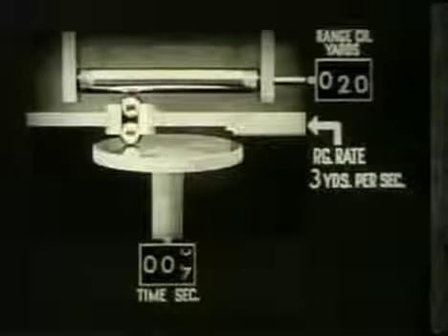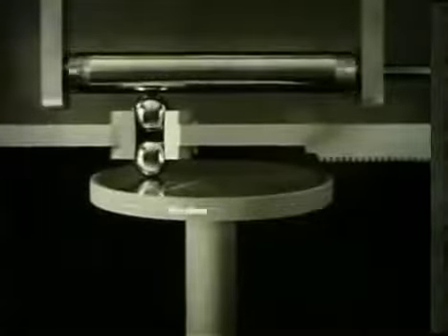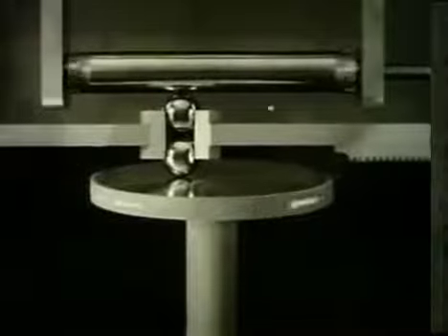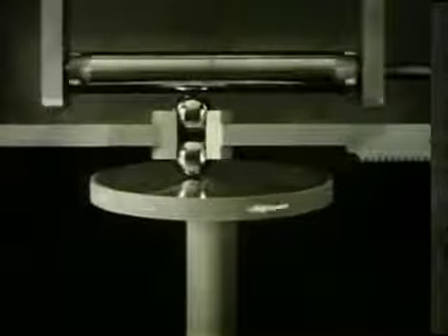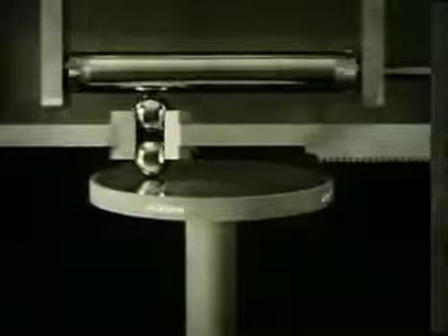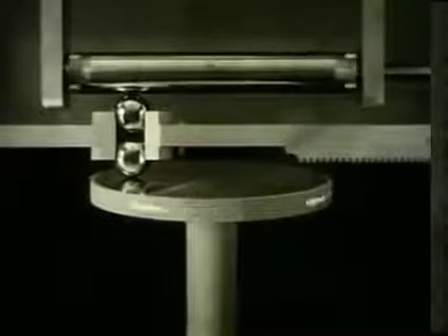A constant range rate is unusual. In most situations, range rate is always changing. This may be regarded as a progression of range rates, infinite in number, and with the integrator continuously computing each instantaneous change and adding it to the total output.